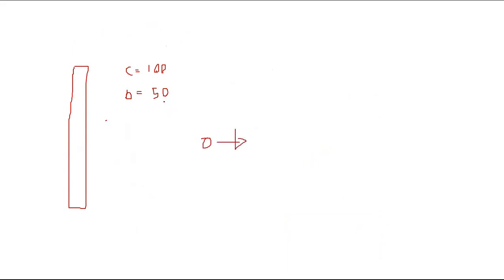It's like this. Let's say the column is this. Let's say for buckling, you need 50 kilonewton. For compression, you need 100 kilonewtons. So this will fail by buckling, because when you increase the force from 0, it will reach 50 first, so it will buckle and fail. Let's say your buckling force is 200, and this remains as 100.